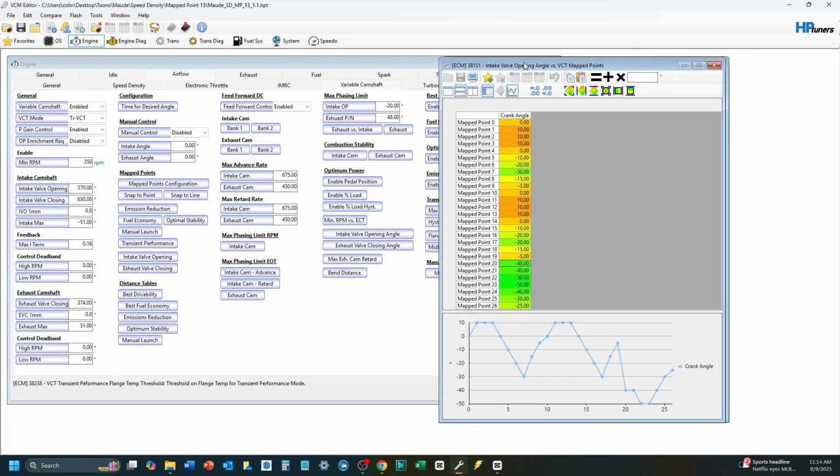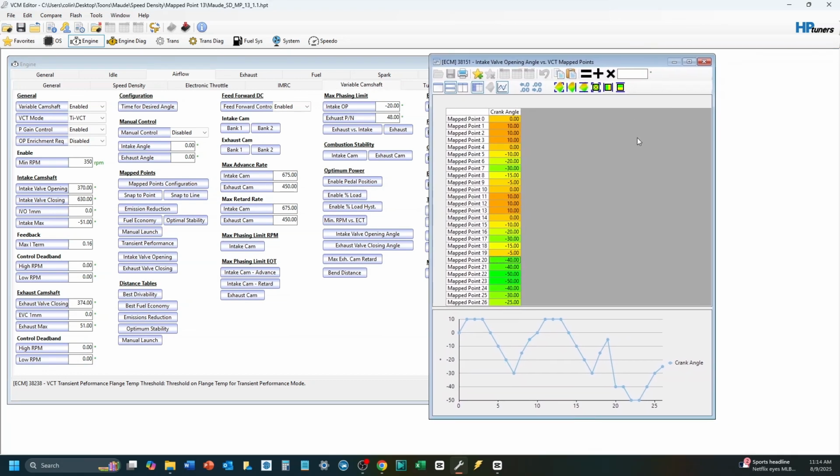That's when it's different, just like MAF tuning is done in a two-step process where you do the low end, right? When that's all dialed in, you go and worry about your WOT MAF tuning. Same thing here. The speed density tuning for these tables, states 20 through 26, this is high power. This is near WOT or WOT itself.